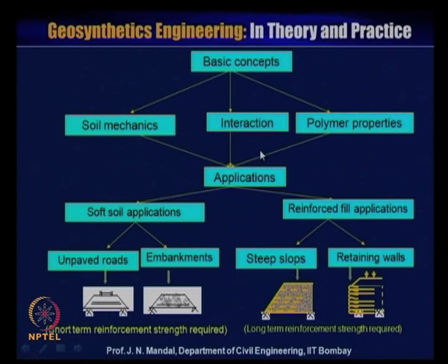And various kinds of applications can be applied to soft soil, like an unpaved road, or if you want to construct an embankment, and these are short term reinforced strength requirements. Another application is the reinforced fill application, that is steep slope or retaining wall, and this is a long term reinforcement strength system.